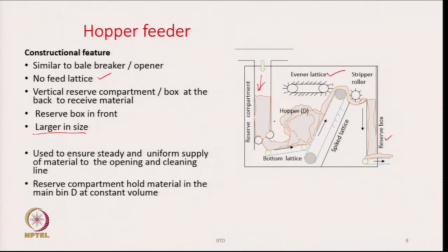So, this hopper will store lot of material here. Working principle wise, it is similar to the bale opener. We also get little some amount of opening actions in between the spikes of the Evener lattice and the spike lattice.